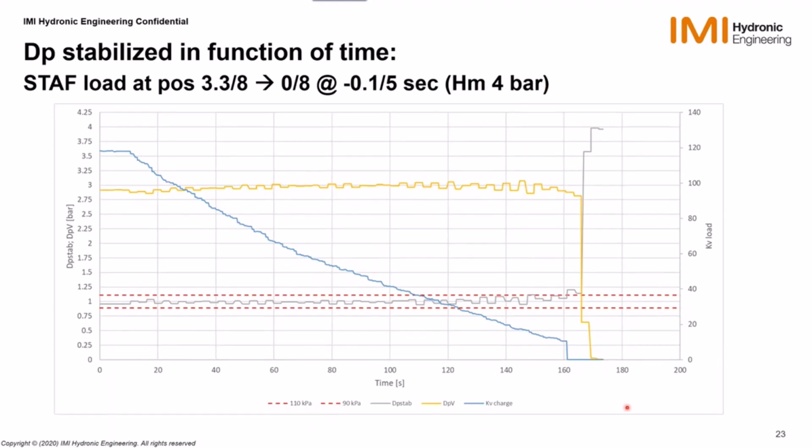So this is what I explained exactly at the beginning here. An electronic delta P controller is not a delta P controller that can prevent the available differential pressure from going in all circumstances on the valve. It will not be able to prevent that. It will let it go when the load goes to 0.